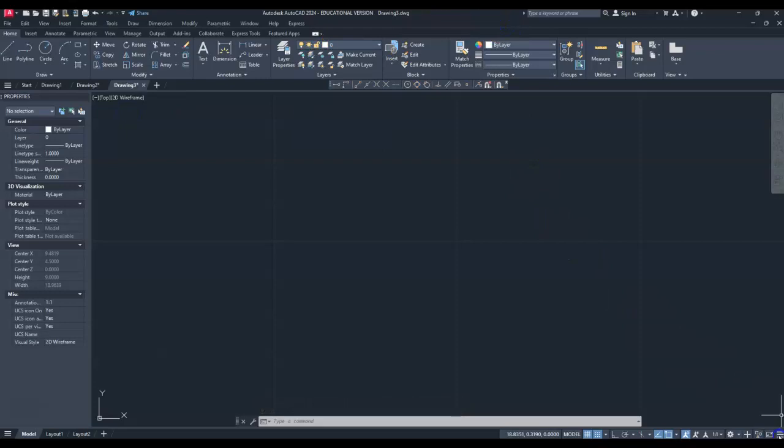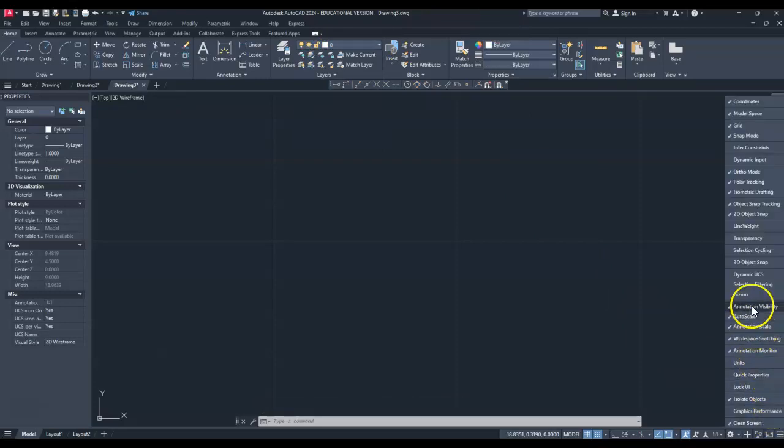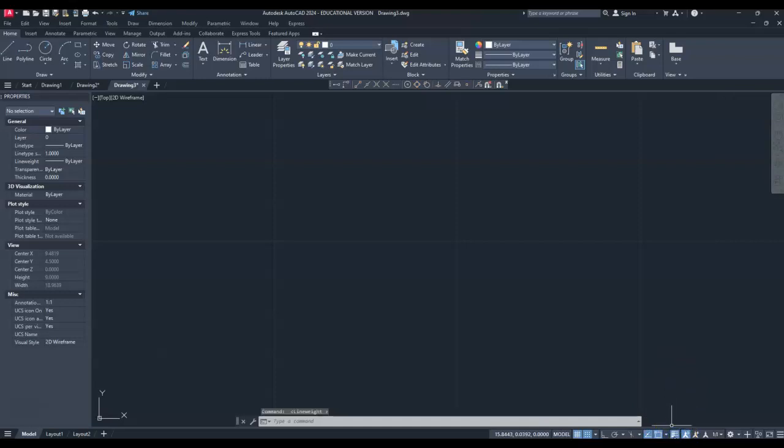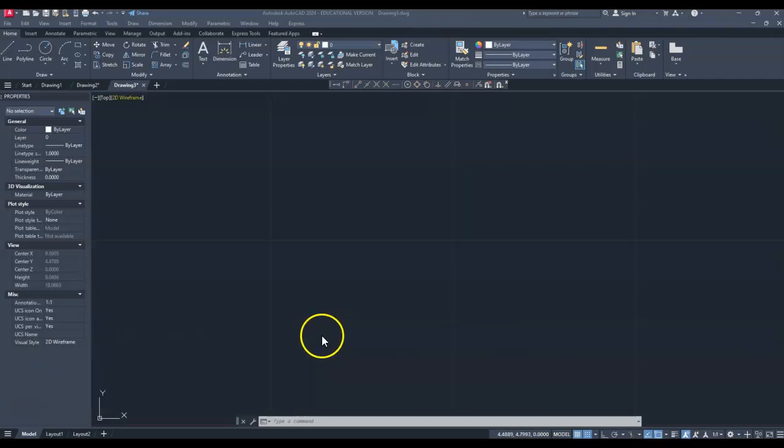Next, I'm going to choose my line weight option. Okay, so I can turn on line weight. You'll notice down below a new indicator shows up. As I'm drawing, my line weight will appear either as a default, like the basic simple line that we've had so far, or will actually show the new weight that we chose in the layer settings. This is handy if we want to see the precision components without the thicker lines being in the way. Now I'm going to start creating my construction lines.